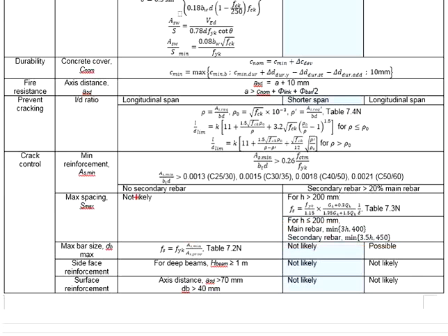Let's say now you would like to check for the maximum spacing for the beam. A typical beam will have a thickness or height of more than 200 mm. Therefore, these equations are also applicable for the beam, just that the maximum spacing is likely not exceeded.